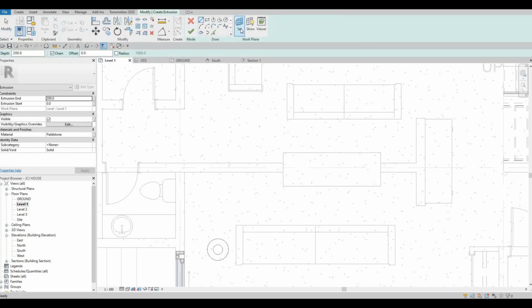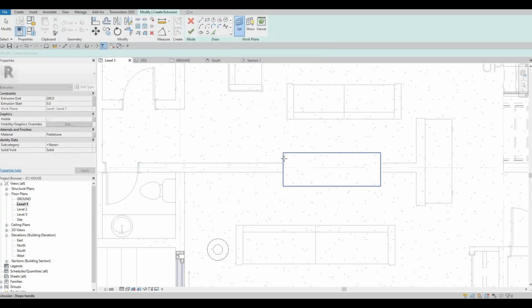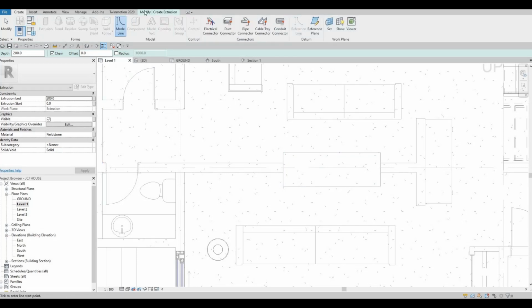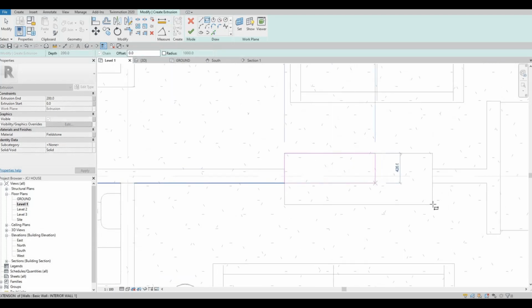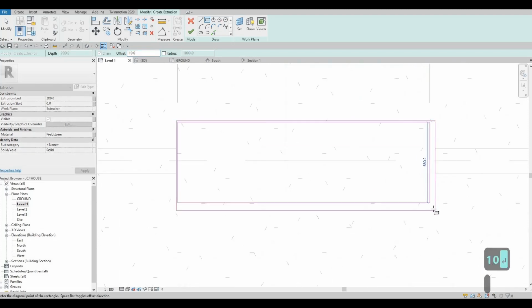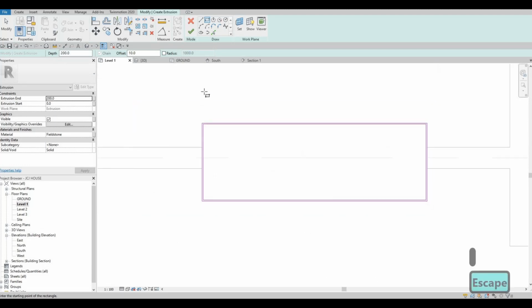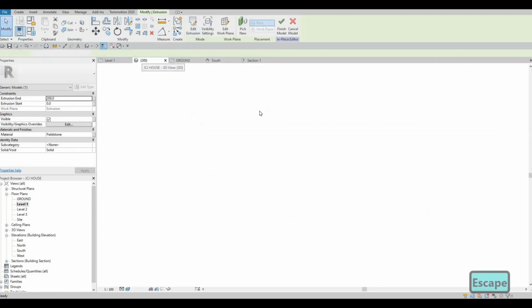and then after that we could have another extrusion. We need to set this one, pick a plane on top of this plane, and then let's extrude this one as a glass. So here we could just have this one, and then another offset of this 10, and then from the inside, that's the glass. Click finish, and then let's look at it at 3D.